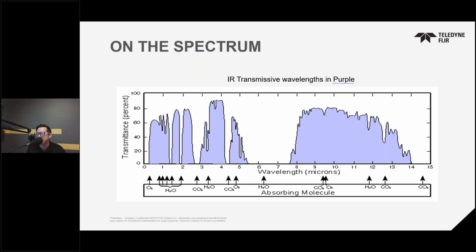So going back to IR detectors, most of the detector materials we've discussed actually do respond to wavelengths in the 5 to 7 realm. But as you can see here from the chart, this is a veritable no man's land for IR transmission. So you might wonder what's going on in that 5.5 to 7.5 kind of range. And that's really where the water vapor exists in the atmosphere. There's just a lot of water vapor in that 5 to 7.5 range there, and water vapor absorbs IR energy a lot, and that's why you don't see transmission there.